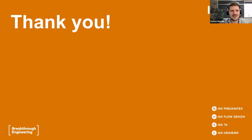Even though nowadays we have some good methods to do that, sometimes when I receive projects here in my department and we give suggestions, we say, oh, you have too many valves here. Why don't you break up into some small branches and run them in parallel here? And you decrease to like 12, 15 valves maximum per branch. There's not a fixed number for that. It depends on how much available pressure you have reaching that branch, and what is the difference in available pressure when you compare the first equipment to be attended and the last one.